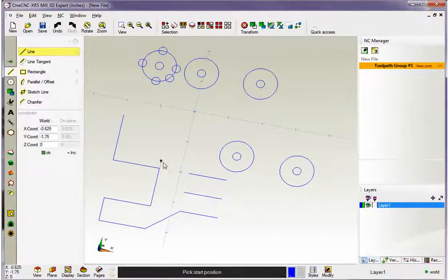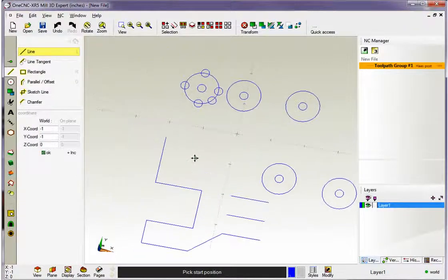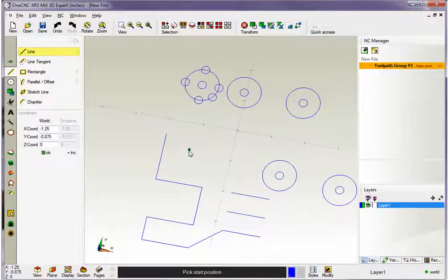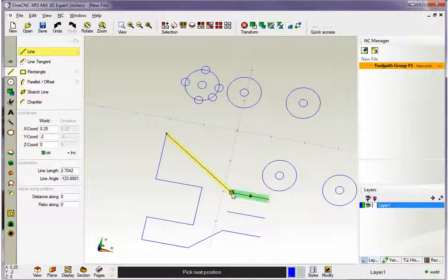Alright, so when creating points, arcs, and lines, you can also create geometry at existing locations. We learned that earlier when we were creating points. So it's never been easier, for example, to join lines. Let's say I want to create a line that starts here and terminates there. It's real simple. Just wait till you see the little symbol there, the little square. Left-hand click, come over here, wait till you see the square, and left-hand click. Now when I'm done with that line, I'm going to right-hand mouse click.